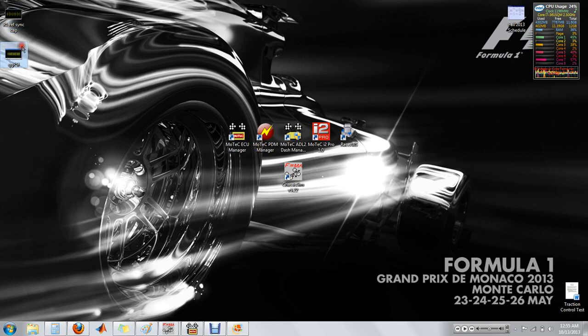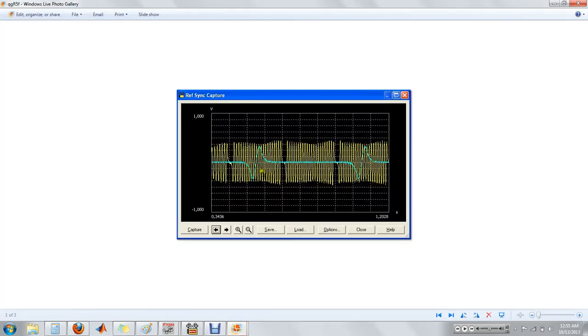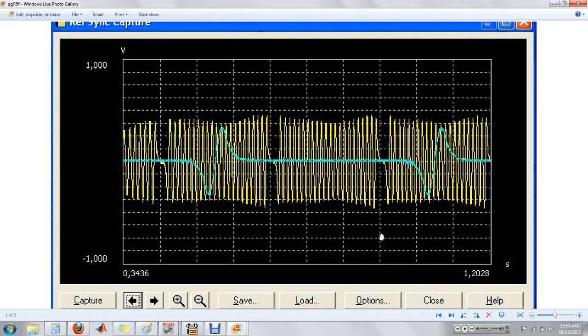Now looking at another example. In this case, a bit bad resolution, but the audio still gets across. If we're looking at our sync sensor, we see that the zero crossing occurs on the sharp upward increase. So in this case, this would be a rising edge sensor.